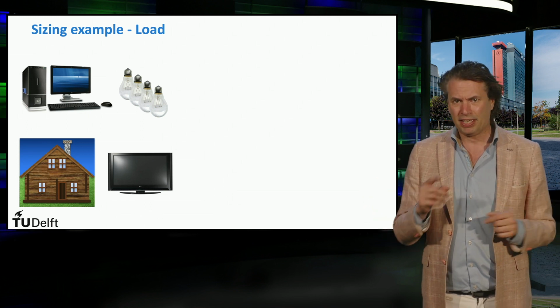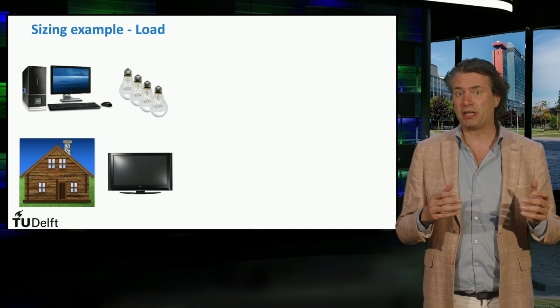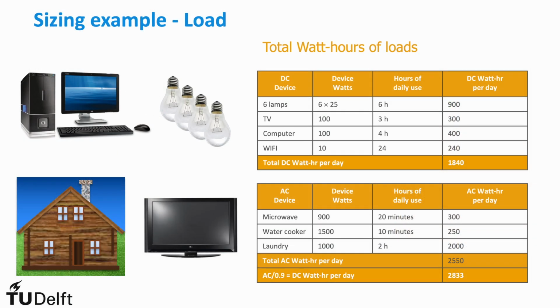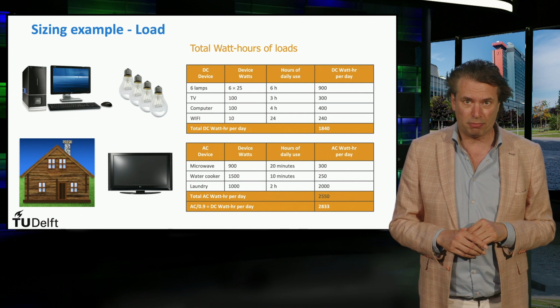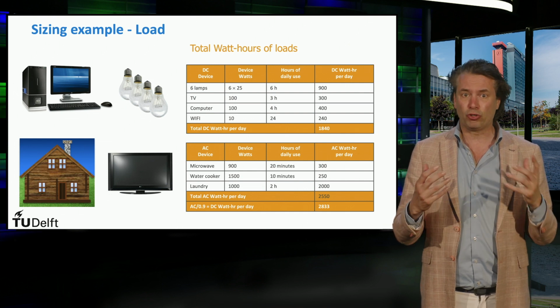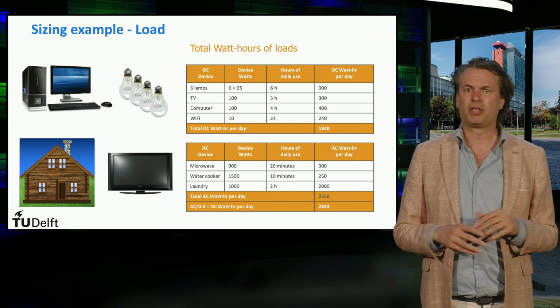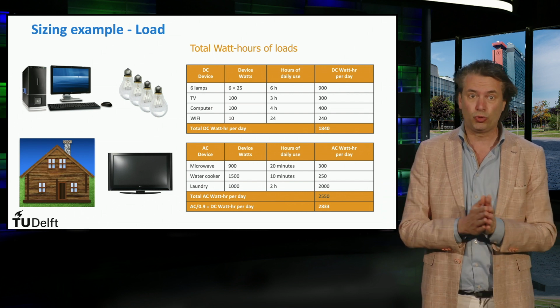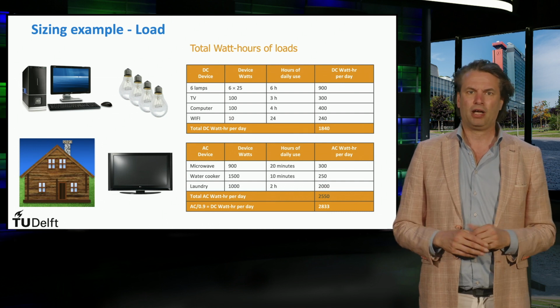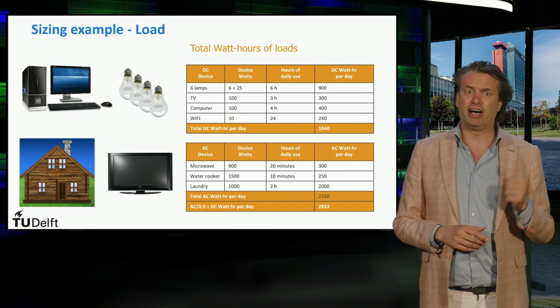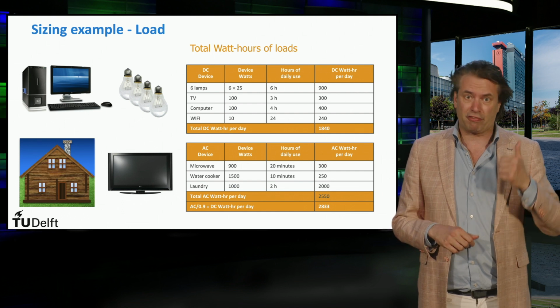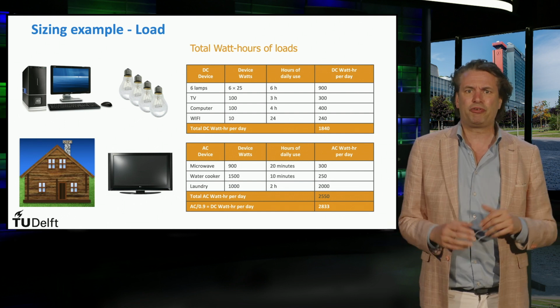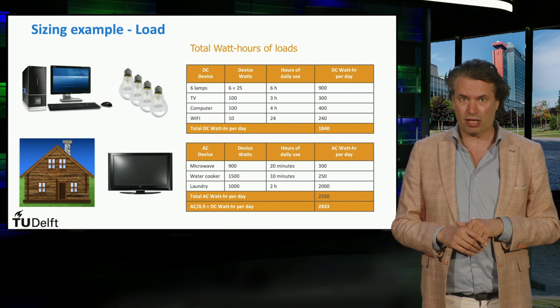Let's begin. This method follows a step plan to complete a PV system. As introduced in the previous video lecture, the first step involves listing all the loads in a so-called load table to determine the daily total load demand in watt hours. A load table basically contains information about the loads that will be connected to the PV system. By filling out details such as the device type, its rated power, and its average daily operational time, the energy requirements of the loads can be calculated.